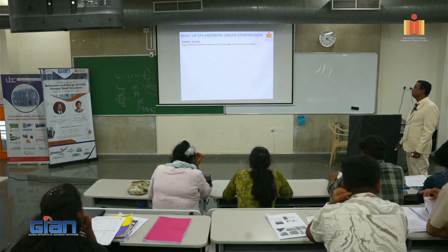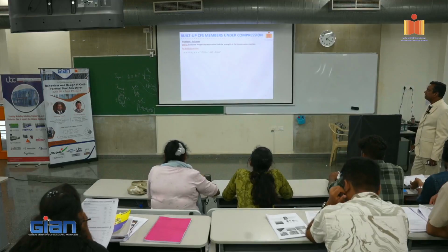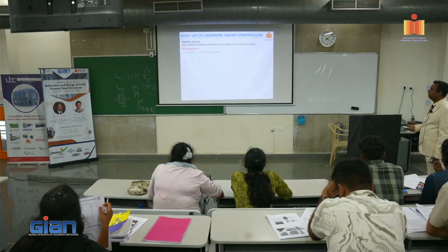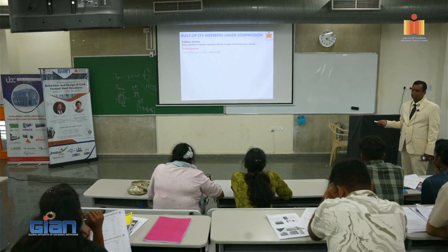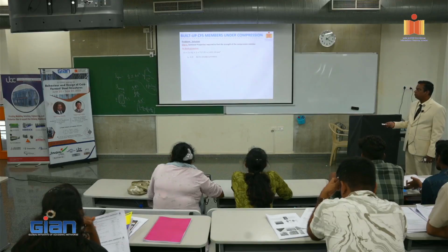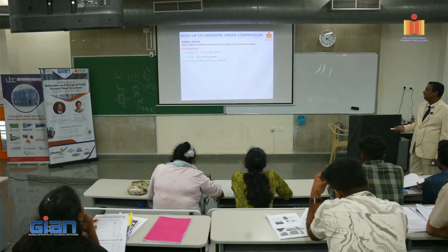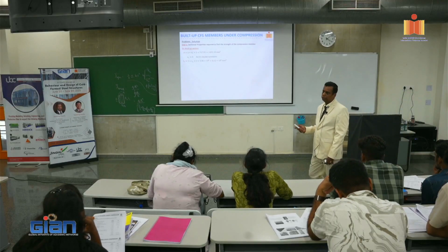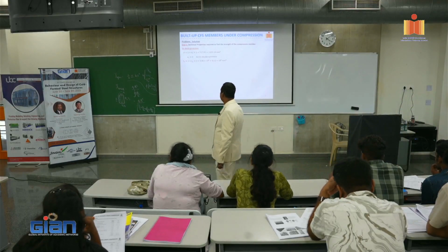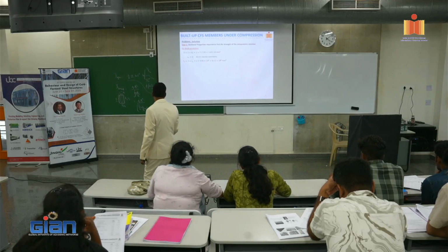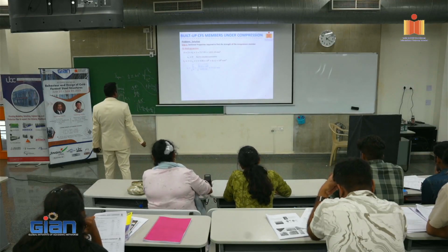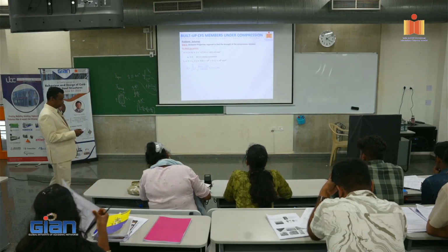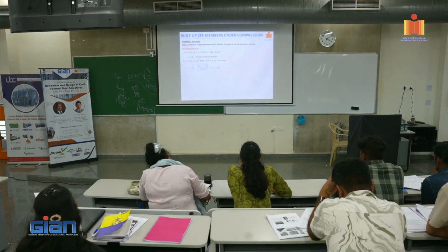Sectional property is required to find the strength of a member. For built up sections, you have A equal to 2 into Ai. So 2 into 717.59, it becomes double the value. X0 equal to 0 because it is doubly symmetric, and Ix equal to 2 into Ix individual, right? So we get 2 into 4.06, this is what we have, and then we can find out Rx equal to Ix by A, right? So we get this one, this is 75.22.